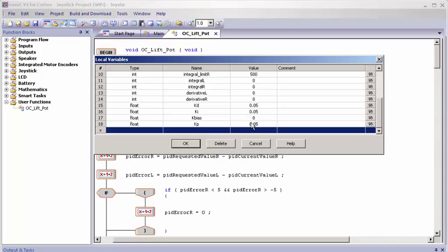I can tell you now though that the proportional is usually the highest. So the Kp constant is usually the highest constant out of the 3 that I'm using right here. Almost always. So just make sure that you do not use these values, because they probably won't work. They're very small. Make sure you use larger values made for your robot.